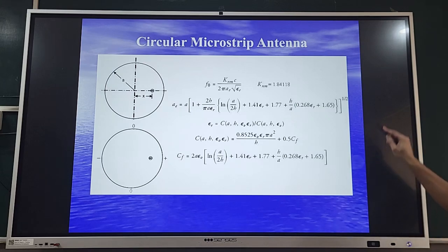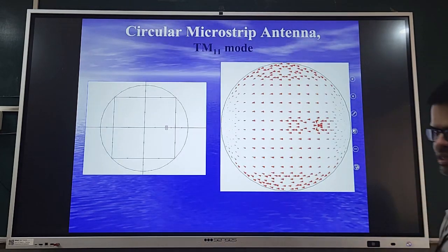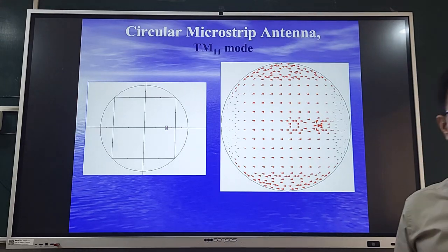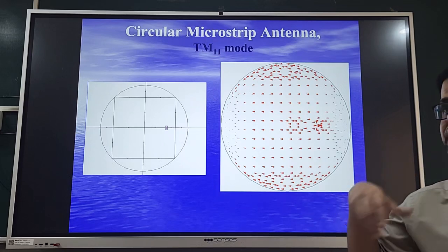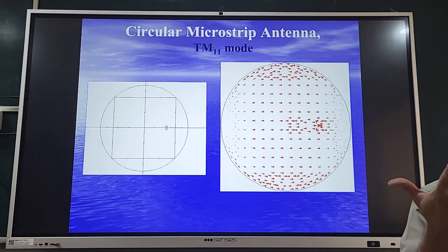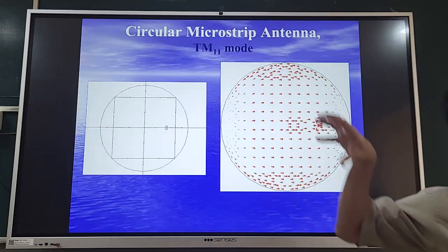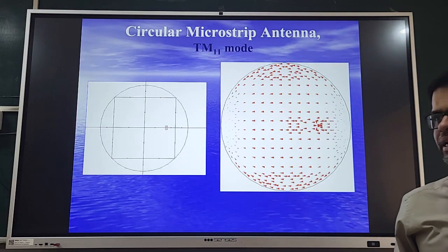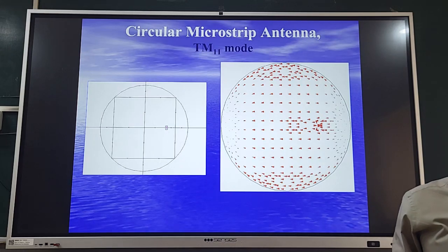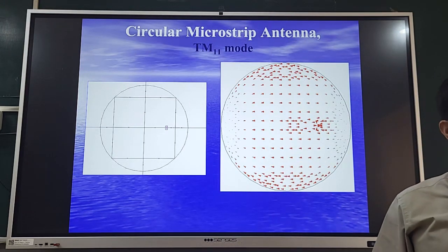Okay, so we have talked about the circular microstrip antenna, its radiation pattern, and the impedance matching. There are no direct formulas available, but if one can design it, it can lead to a conference publication where we come up with closed form equations, by having a comparative study with respect to the rectangular case, to get the equation for X for a given input impedance location for a circular geometry.